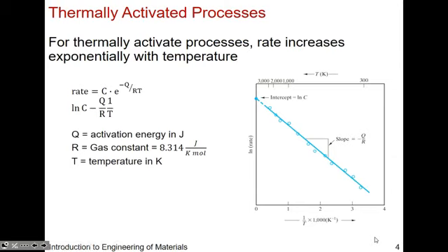Okay, speaking of thermally activated process, we revisit our friend the Arrhenius equation, right? Typically, it's some rate, and it's related to some activation energy Q divided by RT. So the T is your temperature in Kelvin. And here I write C as some proportionality constant. It could be anything, really. But that's just it. And the typical curves or plots that you see when it comes to the Arrhenius plot, it looks something like this.